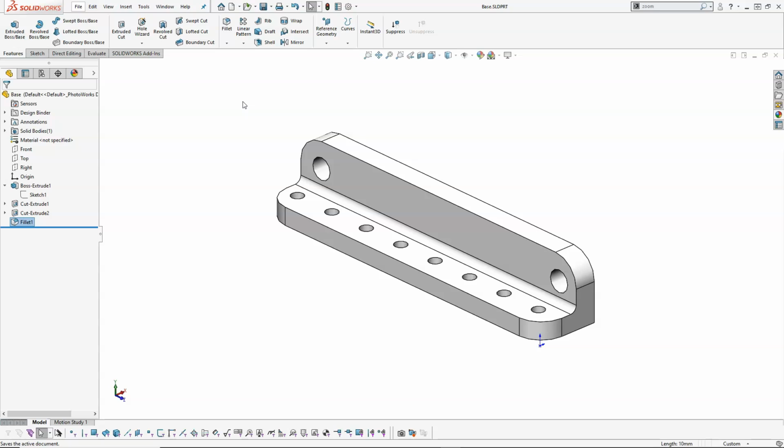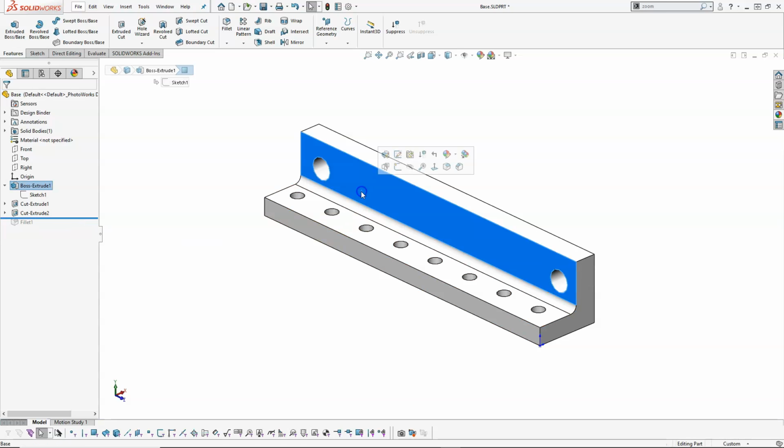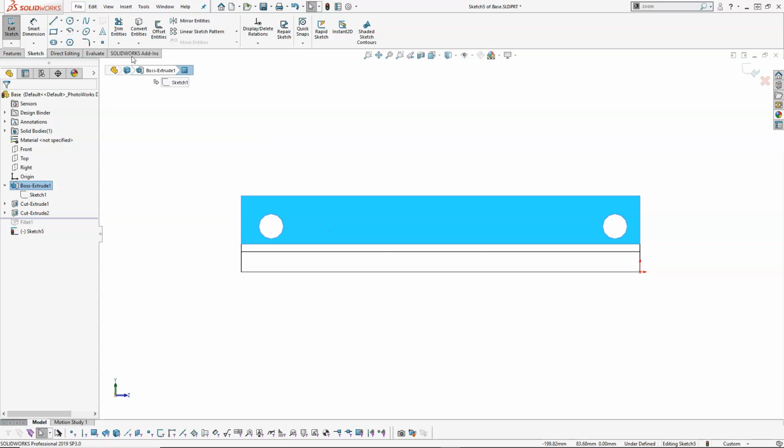And now we're going to put in the text. Alright, so I would still like my fillets to be last, so I am going to look for that bar. The rollback bar at the bottom says I want to treat as if I hadn't created the fillet yet. So when I open up the next sketch, and again I'm picking on a planar face, opening up the sketch, we're going to go into text.